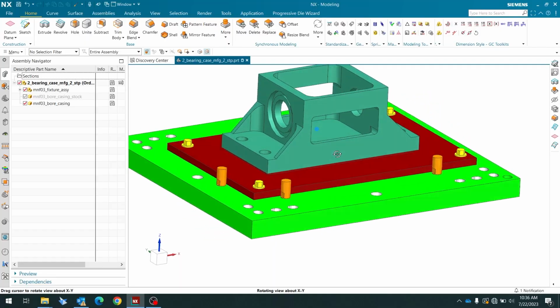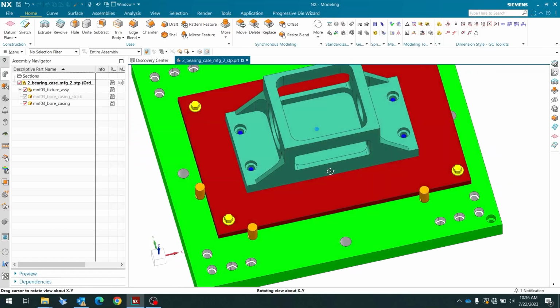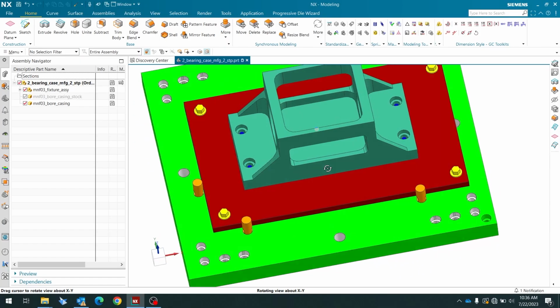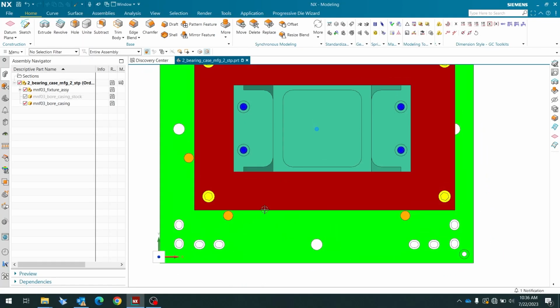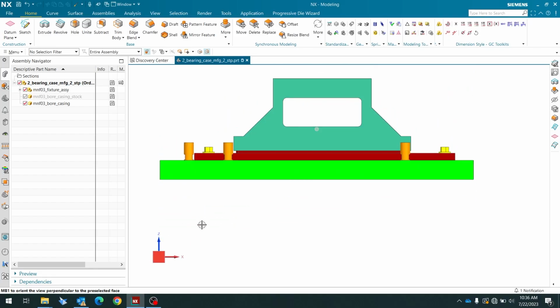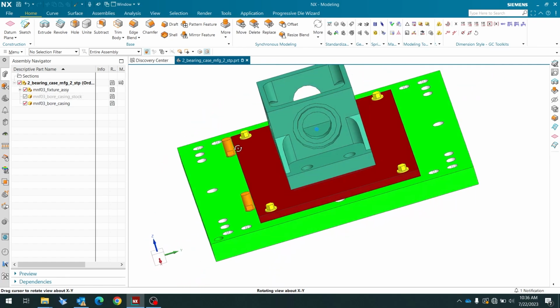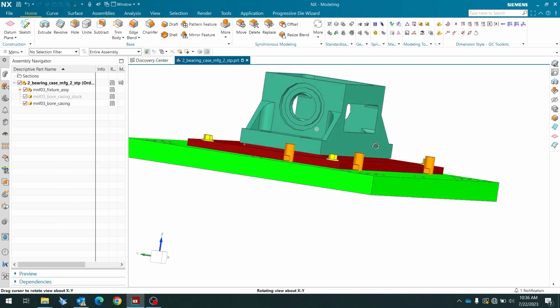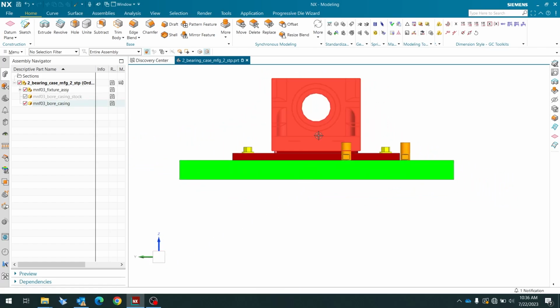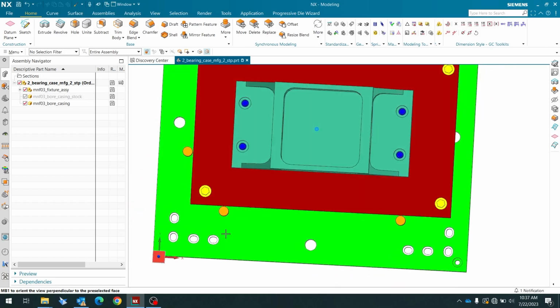If you look here, generally it is machined in different setups. This is the first setup, where we can machine this pocket and create these step holes. After that, this is our second setup, and this is our third. To make this collar structure, this is our fourth setup. So this component can be machined in four setups. Initially we will go with machining of this particular pocket.